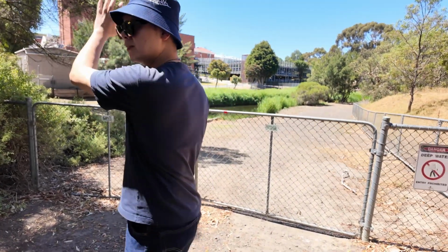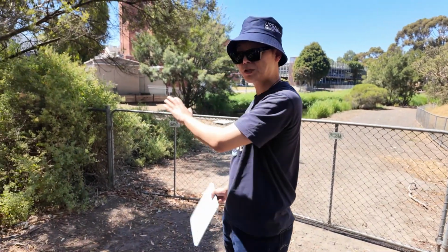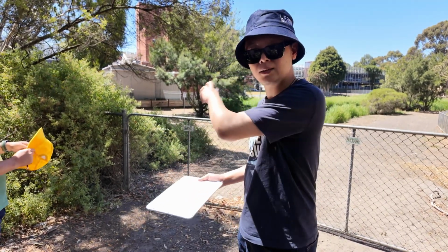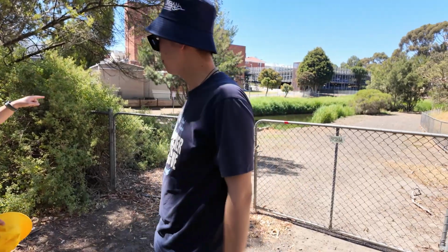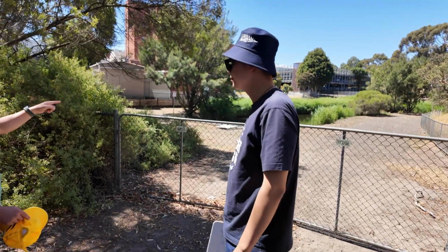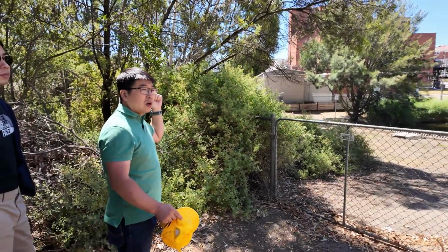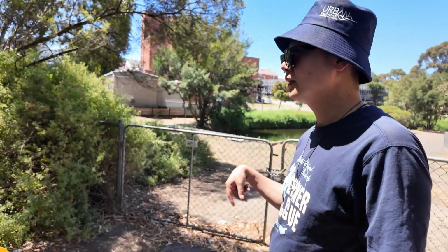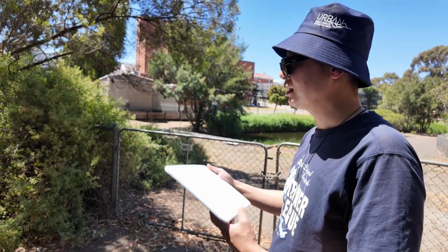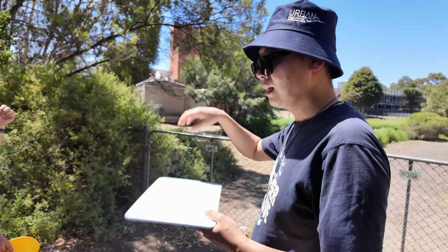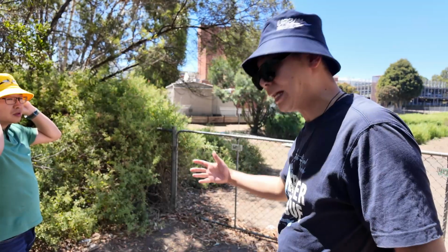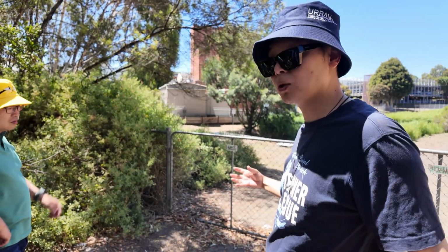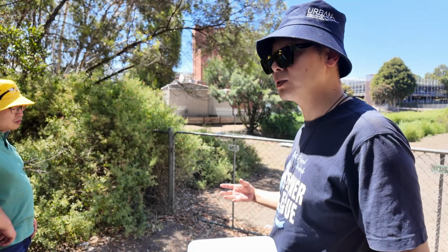So this is the first process of the wetland, which is a sediment basin and the diversion high flow bypass weir in one place. So currently it's dry weather, so almost all the water gets into the wetland first. Yeah, it's dry weather, but the base flow also goes in, right? Because this is a large catchment. Okay. Even though it's not raining, all the basements of high-rise buildings have a sump pump, because stormwater base water goes into the groundwater, right?